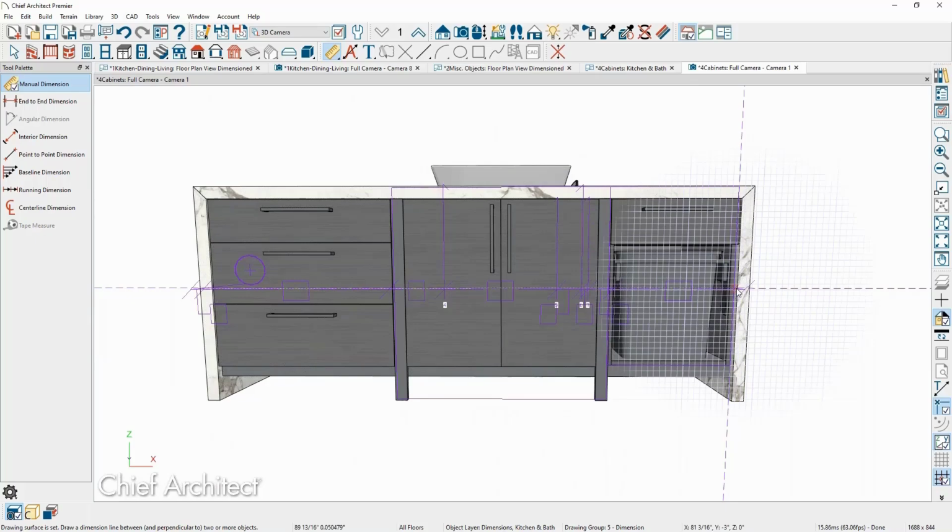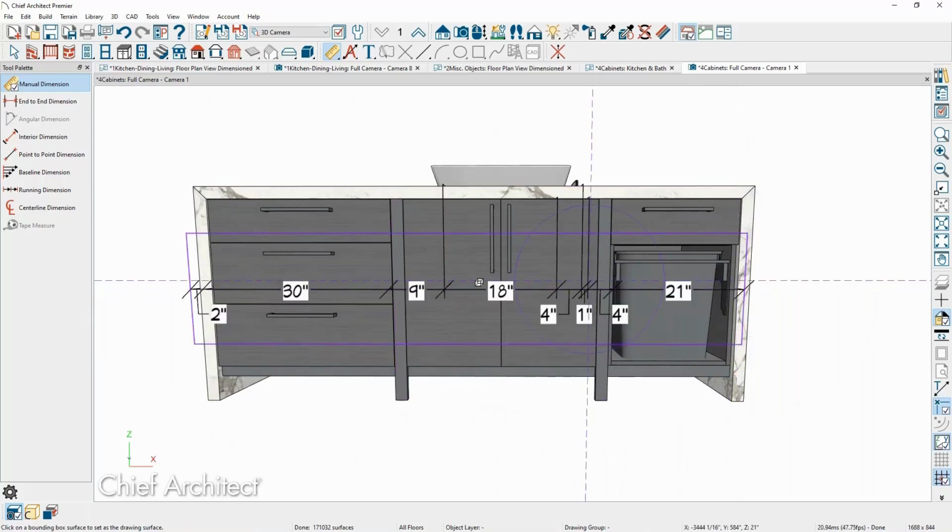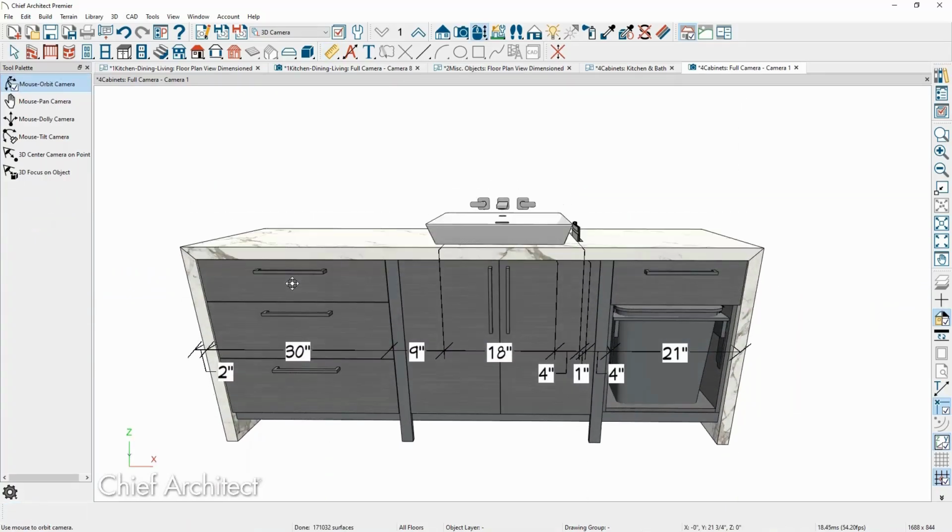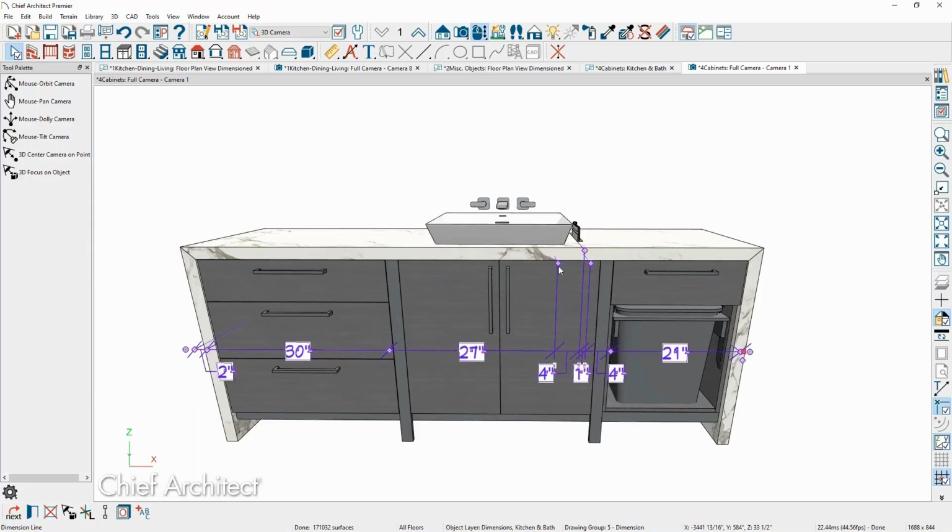And it looks like it's picking up a handful of points. Let's see what we get. So starting on the left and then working our way to the right, we get the waterfall, the cabinet, and it looks like these points here, they're picking up, I'm guessing these are holes in the countertop at the top. Super easy to remove those points. We can simply select on it, come up to the extra diamond handle, and then just drag those off into free space to eliminate them. So there we have that cabinet.